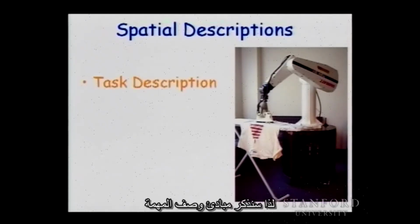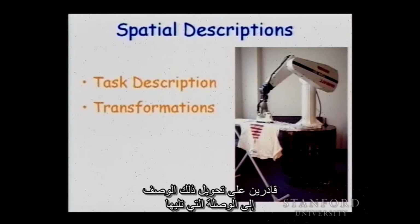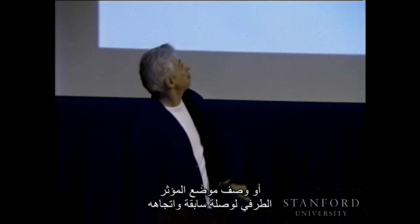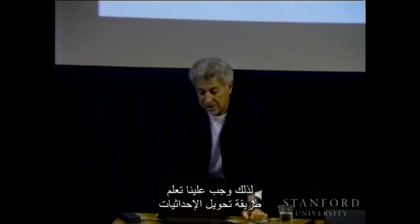So we're going to go over the basics in describing a task, the models that we can use to determine the position and orientation of the end effector. Then obviously when we determine the location of a link, we need to be able to transform that description to the next link or to describe the position and orientation of the end effector in a previous link. So we really need to handle transformations.